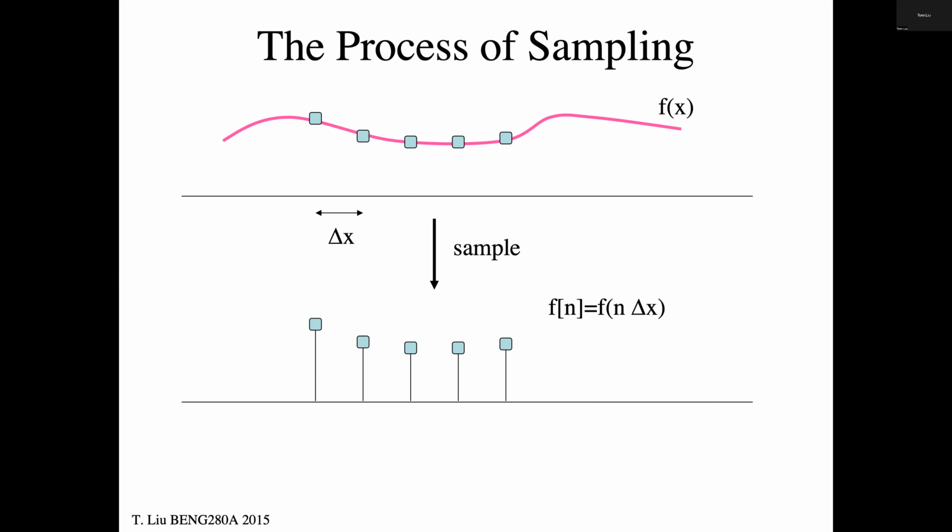There's two ways to do it. One way, and it's the most common way, 99.9% of all scanners do this. You have a material that when X-rays impinge on it, they cause light, like a fluorescence or some other interaction, right? And then at the bottom of that detector, which usually has reflecting surfaces inside a column, you'll have a photodiode which counts up the brightness of the light, and that's your voltage. So that's the intensity of the X-rays that were measured for that measurement.